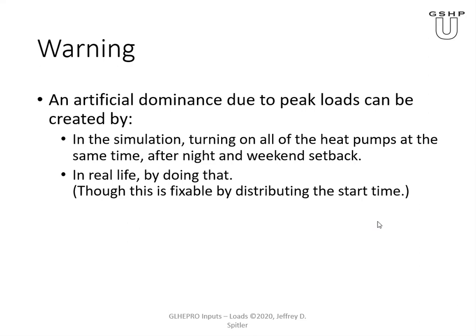But you said this can happen in a simulation. It can also happen in real life, right? And in real life, it's fixable, though, by distributing the start time, and it's fixable in your simulation by distributing the start time. But it's something to keep an eye out for. Some people run simulations that show an exceptionally high peak load, and you realize you had the building off all weekend. In fact, maybe it was Labor Day weekend, and you let the temperature in the space rise to 86 degrees or 30 degrees Celsius. And then at 5 a.m. on Tuesday morning, after a 3-day weekend, you turn on the system, and of course there's a very large cooling load to pull down the temperature, right?